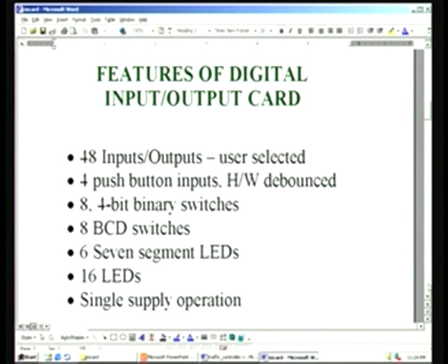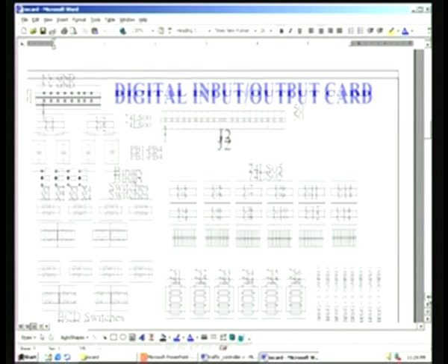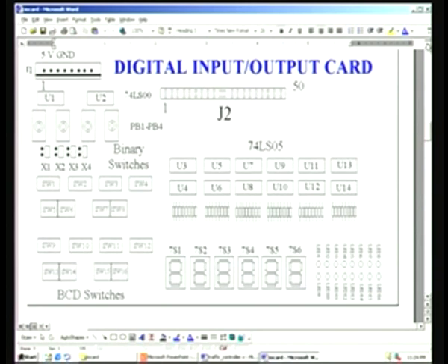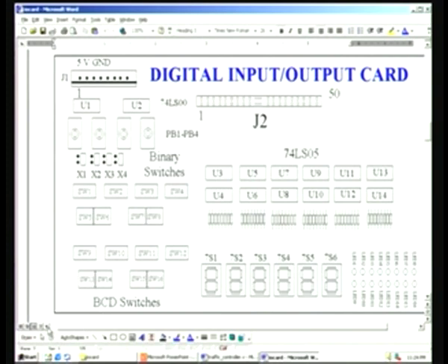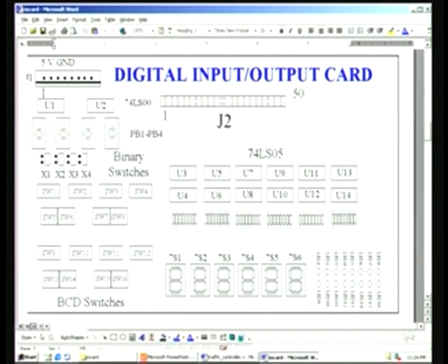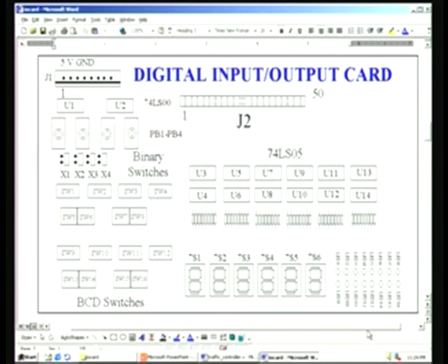And we will have a look at the layout of the IO card. This is the IO card which we see here. This card has a connector which is 50 position and a bug stick male has been put on this board, and naturally you need a female FRC connector to mate with this and interconnect it to the FPGA board on the expansion headers.